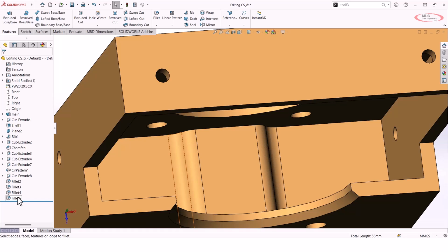You do give a little bit of control up because you don't necessarily know which order the Fillet Expert tool is going to create those fillets in. You do have the ability to reorder them later on, but more than anything, I think this is just a great way to save yourself from having a big headache. If you've got a complex region that you're trying to fillet and you just want to know if it's possible depending on the order of operations, try out Fillet Expert. I think it's great for helping you get out of a jam.